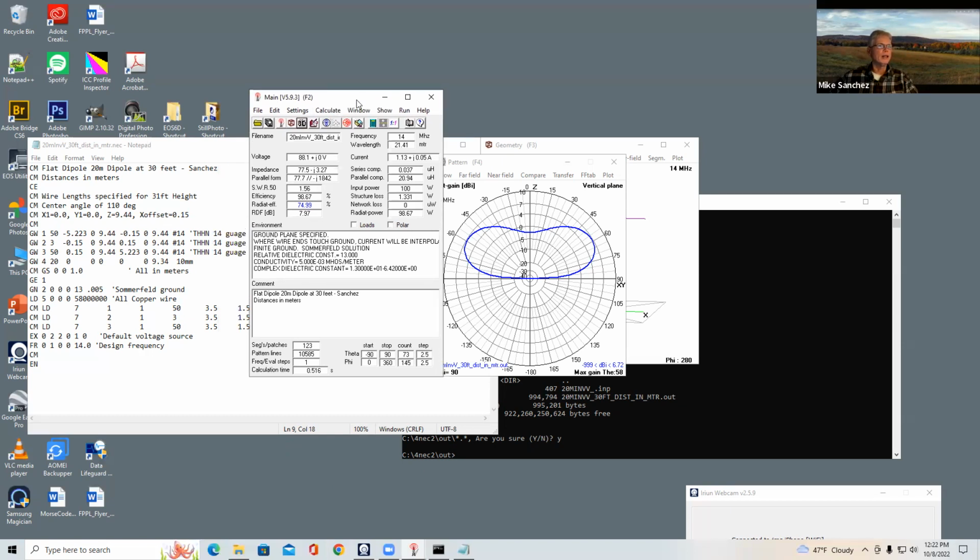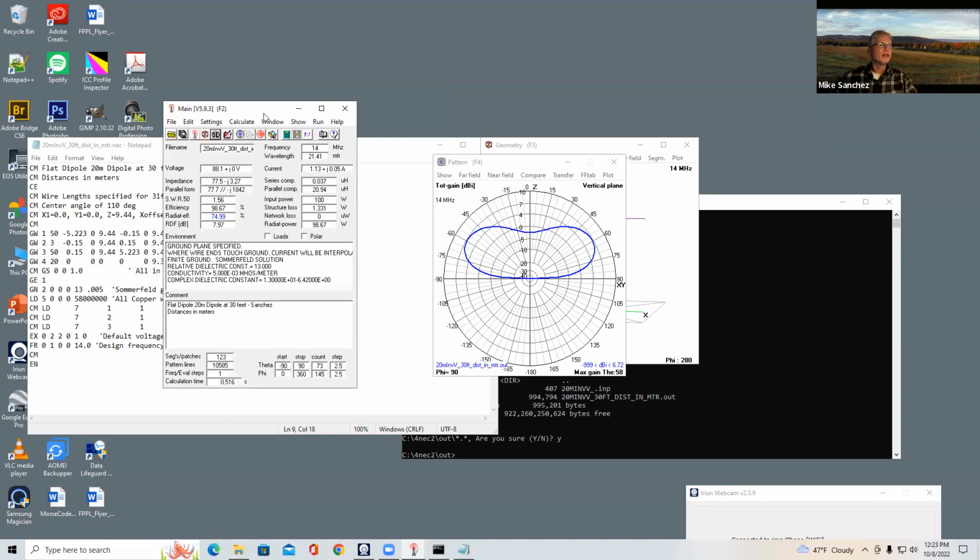After we're finished with this, we're going to add a transmission line. And after we're done with the transmission line and understanding what it does to an antenna, we're going to change the frequency as if we're going to function on Mars, and we're going to leave the antenna alone and just change the frequency to 16 megahertz. Then I'll show you guys how to use 4NEC2's automated capability of generating multiple different kinds of matching sections. We'll match this antenna for 16 megahertz, and then we'll build that network into this antenna. So that's what's coming next week.